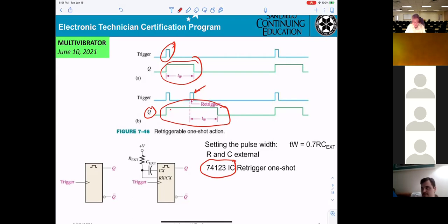That's just for when you go to college and they want to verify that you understand it. In the lab, you connect the IC to a resistor and capacitor, and they ask for the output they want. Your job is to select the R and the C in order to verify the correction.